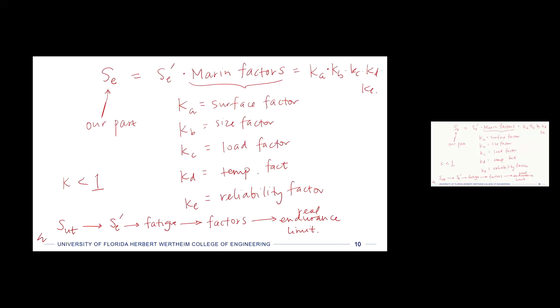So this is in chapter 7 of the book, and it talks about factors that affect these S-N curves. S-N-prime is what they call the S-N curves because they add in a reliability factor. So they call them S-N-prime. And for a lot of the factors, people will try to run a controlled series of experiments. Sometimes they are quantitative and sometimes they're more qualitative. And we just try to assign a factor that generally captures the behavior for some kind of predictive ability. Okay.